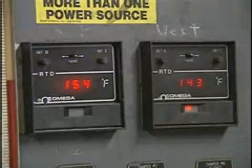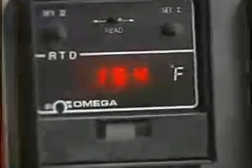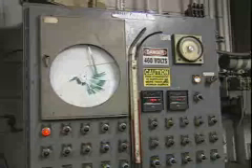The inlet and outlet temperature of the collectors should be checked. The inlet temperature should be compared to the temperature limit for the fabric being used. Frequent exposure to high temperatures can damage the fabric and cause holes to develop. Low inlet temperatures could result in acid, moisture, or organic vapor condensation.